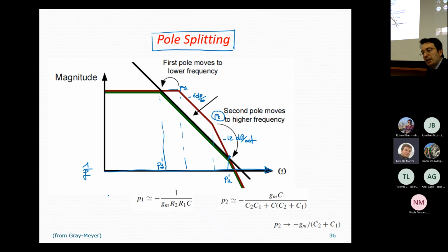We are discussing about PMOSes here, so let's write this way the result. So if we want VSG3 to be equal to VSG6 and 4, this means that since these are all PMOSes and the threshold is the same, the overdrive of transistor 3 should be equal to the overdrive of transistor 6 and equal to the overdrive of transistor 4.